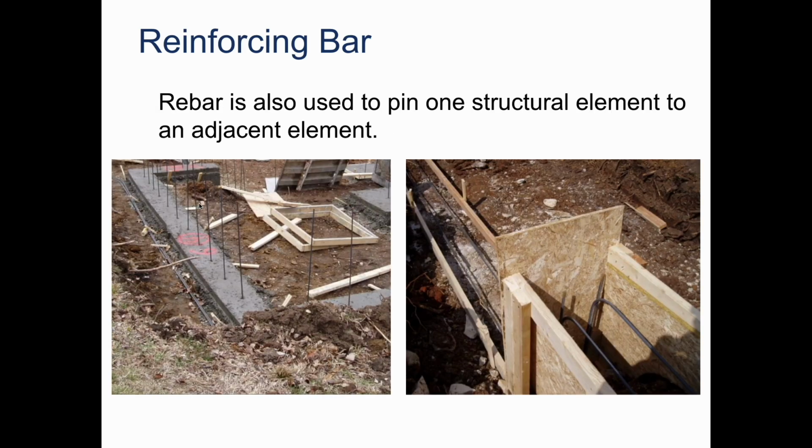All right. Here, you can see that the rebar is also used not only to increase the tensile strength, but also used to pin one structural element to an adjacent element. So in this case, we've got it where this concrete here, this footing, is actually going to connect to a wall.